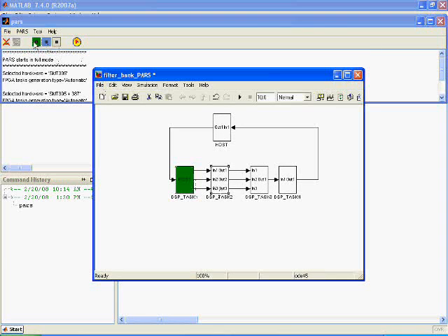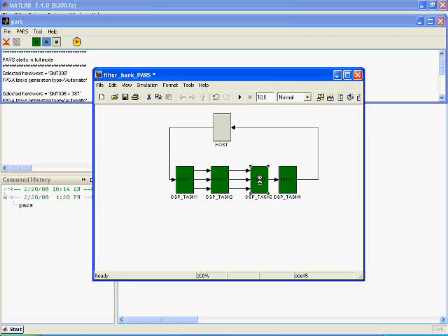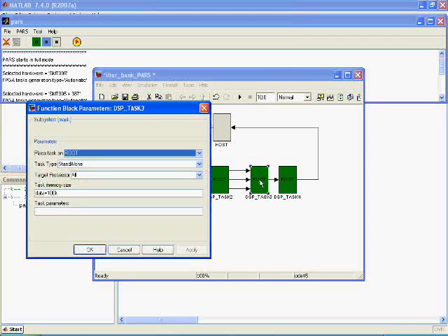to create a DSP task. The subsystem targeting host is then selected at the end and turned into a host task as shown. Note that all DSP tasks are green and refer to the root. I am going to select the 3rd task and change it so that it will not be placed on the root but on the 2nd DSP.